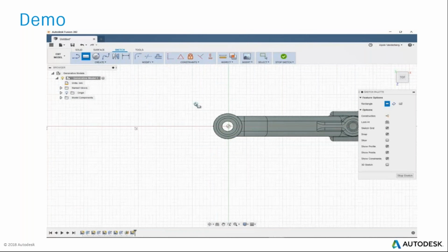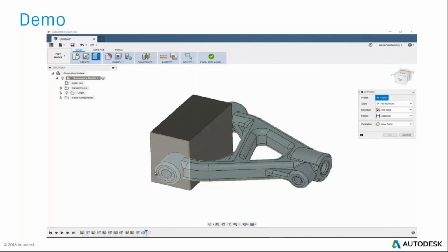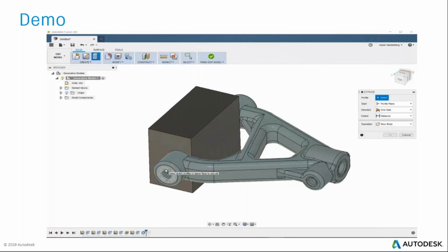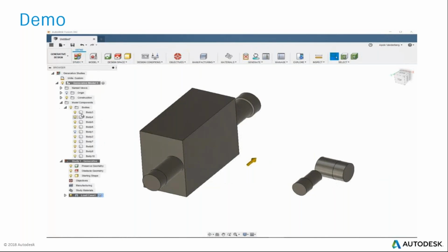As I mentioned, we need some sort of preserve. So this suspension has to rotate. There might be some frame members in here. We might need as well some avoidance regions for the mounting hardware that would go around the bushings, getting those bolts and whatnot. So once we have all of that built and projected, then we can go in and start actually defining this space. So picking those preserve regions, those that we want to keep. We can select them, and as we assign them, they'll show up as green.